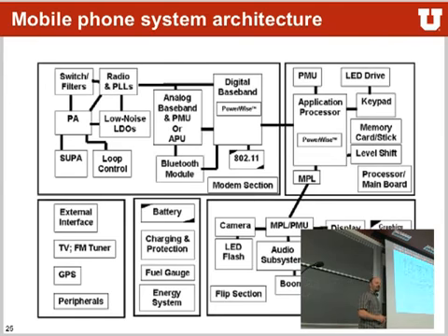Phones are really complicated, actually, if you look at them. It really depends. Some systems can handle it themselves and others can't, so you have to have something else tell them to shut down. Exactly. Many higher power processors are not very good at sleeping. So you have another processor that's really good at sleeping, turning the other one off or just shutting it off and turning off its power so it can't do anything anymore. And when somebody hits the power button again, it turns it back on. So stuff like that happens, and that's what a power monitoring chip is doing.